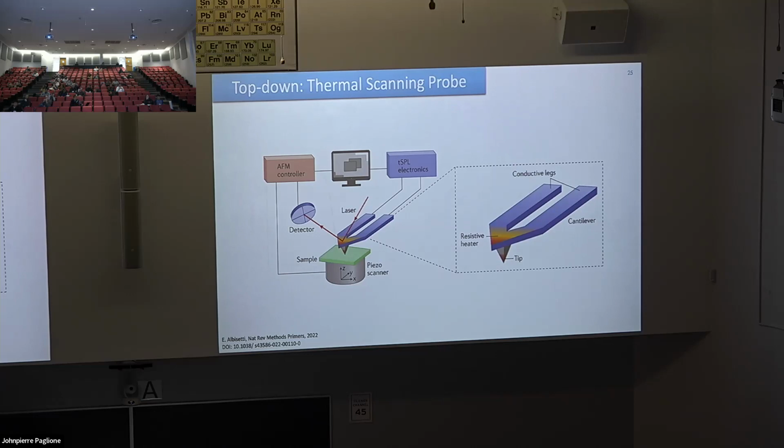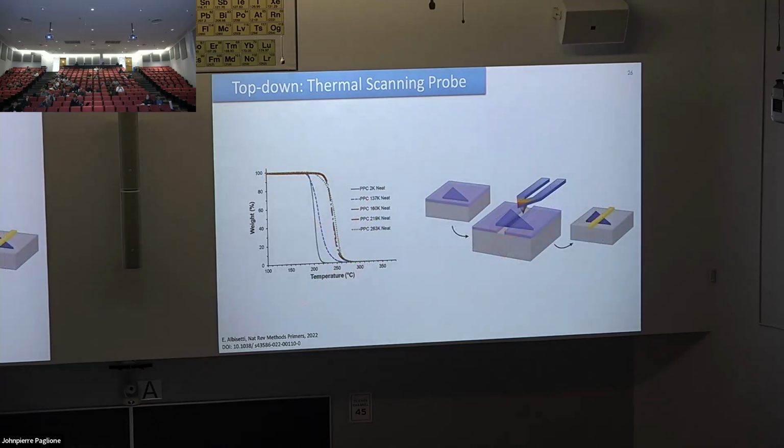But if you repeat this with ultra sharp AFM tips, maybe you get to the point where heating becomes an issue. The good thing is that the kind of resists you're using for this evaporation technique are special. You have a graph here which shows the temperature at which the resist is heated, and how much is remaining. You can see it's a fairly narrow range between the resist being fully there and fully evaporated. So I think this is also a saving grace in terms of how far out the patterning itself extends.